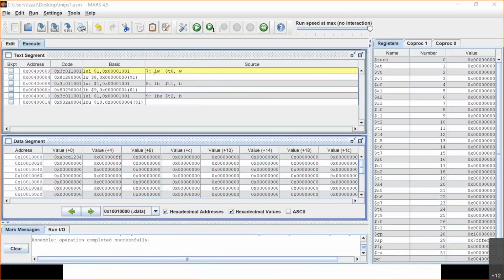So it's going to initialize the lower 16 bits, and the upper 16 bits are going to remain empty. But my address is a 32-bit value. So what I'd like to do is initialize all 32 bits, not just the lower 16 bits. So I use load upper immediate to initialize the upper 16 bits, and then I can use add immediate to initialize the lower 16 bits. Or in this case, because I'm using this as an address to a load instruction, I'm not jumping to it or anything, I can simply use the offset to represent the lower 16 bits.